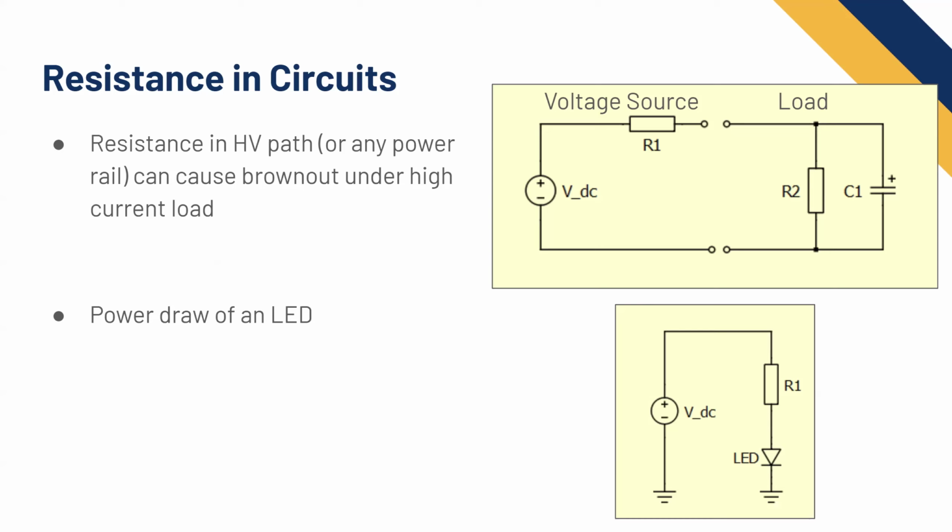Does anybody know how we got from this one to this one to this one? Yeah, how? Because V is equal to IR. Exactly. Ohm's law. It's coming back already. It's already paying off. So if V is equal to IR, we substitute IR into this, then you would get I squared R squared divided by R, so I squared R. And then if we separated this, you have I times IR, and IR is V, right? So now we have IV. So you can substitute between all of them.